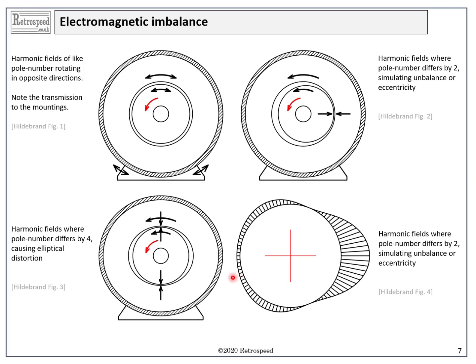In the next slide we can see why this is such a good introduction to the subject. On the right hand side we see the effect of a radial force resulting from two rotating flux waves whose pole number differs by 2. At the bottom is a construction showing the typical shape of this force field. Of course it is idealized, but the main point is the resultant unbalanced pull in one direction. Depending on the origins of the field, the resultant force can rotate in either direction, and it can even be stationary.